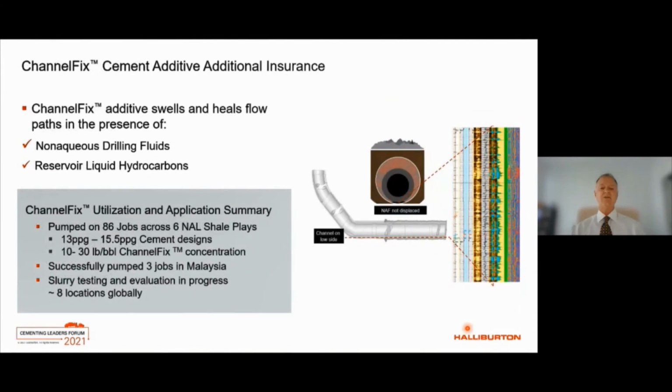Recently, Halliburton introduced an additional tailored cementing solution that should be considered when sustained casing pressure is of concern. This solution is Halliburton's Channel Fix cement additive. The Channel Fix cement additive swells and seals any flow paths when exposed to non-aqueous drilling fluid, hydrocarbons, or methane in a supercritical state.